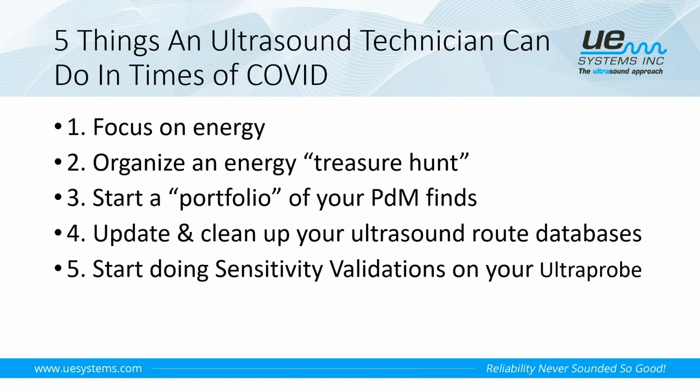And then the final thing, again, it's something that we all kind of lose sight of the importance of, and that's doing sensitivity validations on your ultraprobes. If you've ever been through any of our level 1 courses, you know that we emphasize the sensitivity validation test, but it's just a test or a way to check to make sure that our ultraprobe is still within calibration, to make sure that we're getting consistent and accurate readings.